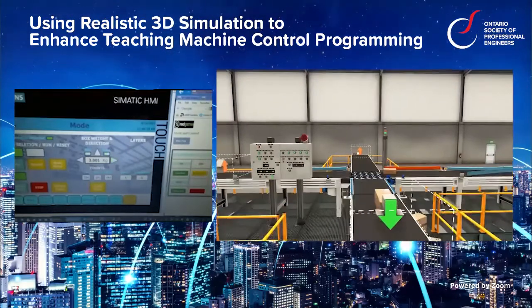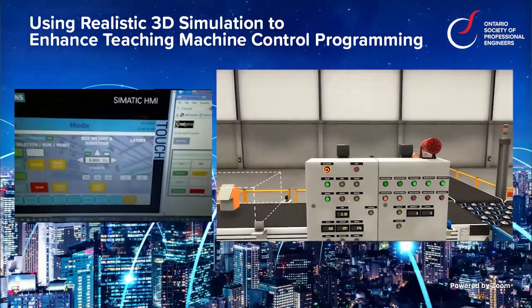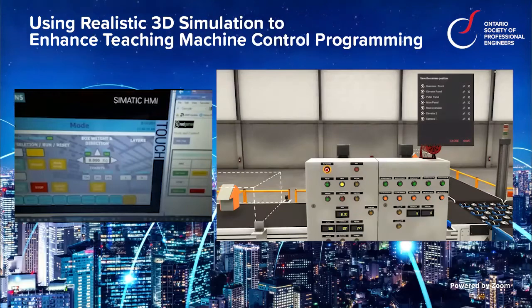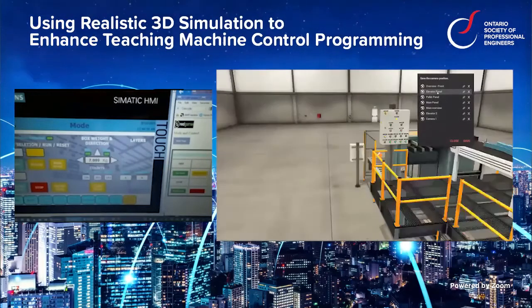Okay, so what we can do is demonstrate some manual motions here. So I'm going to go ahead and stop the system, put it into manual. Oops, have to hand auto reset. Put it back into manual mode, and I'm going to go over to the elevator and demonstrate some manual functionality. I'll do that first from the panel. So I go to the elevator panel.